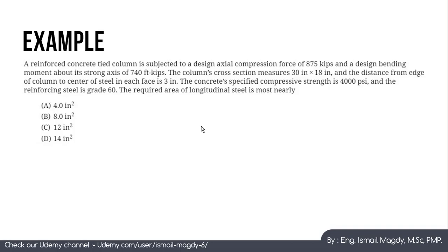So we will start first by calculating gamma of this concrete section so we know which interaction diagram we will refer to. Gamma equals (h minus 2d) over h. All of these equations, of course, are mentioned in the reference book. I'm going to show you in the end the chapter for structural engineering in the reference book, so you know what is exactly included in it.